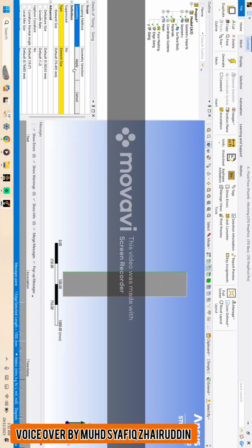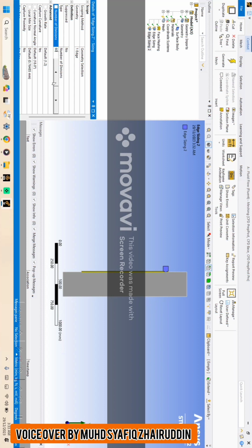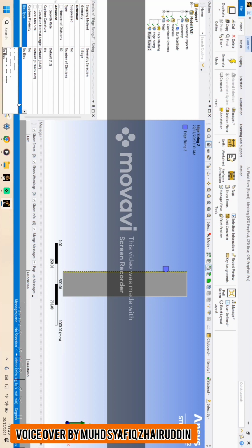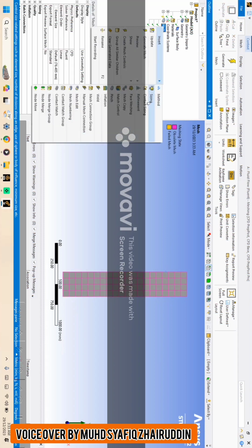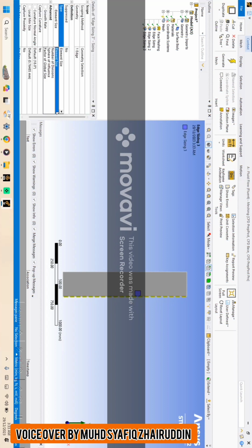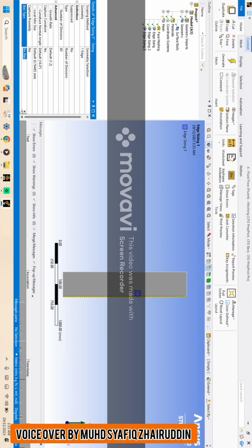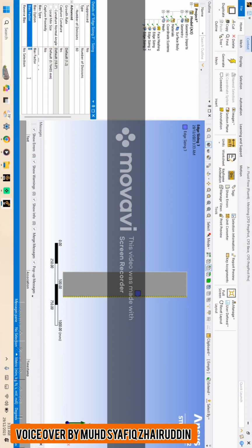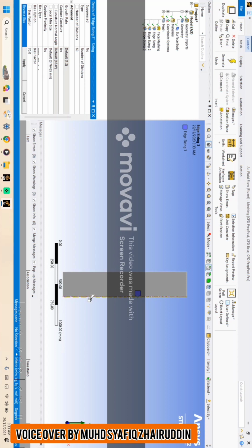and then for the left boundary we choose 60 number of divisions, and the bias type is bias factor and the value is 70. Now insert the sizing again, apply to the right boundary, the number of divisions is 60, and the bias type is bias factor and the value is 70, and you click apply.